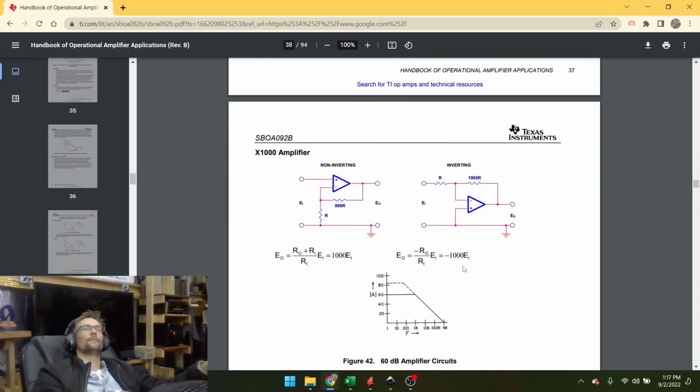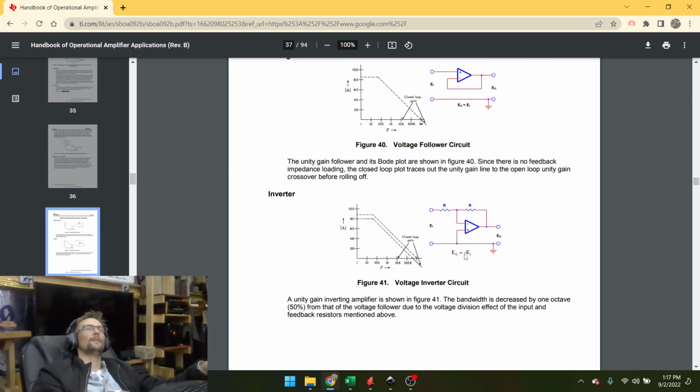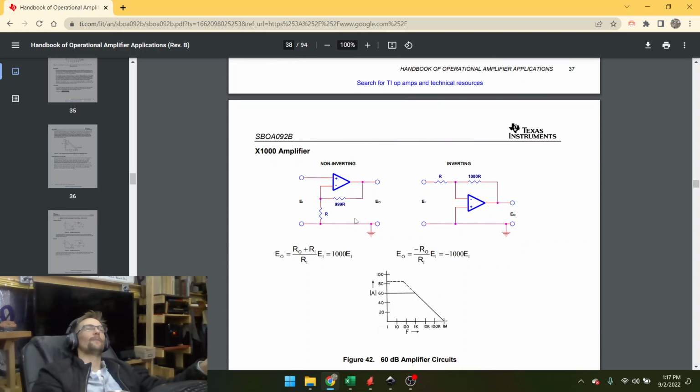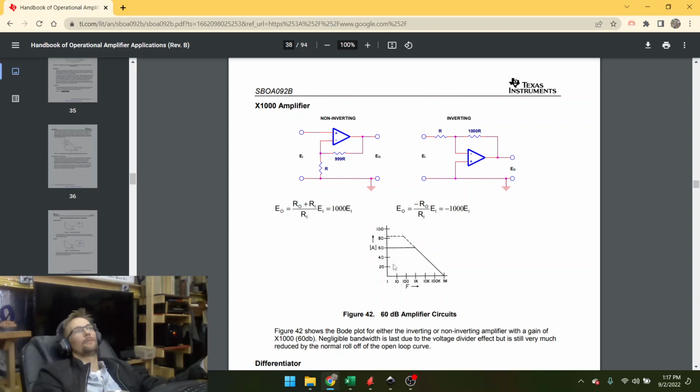So, yeah, that's just one of the things electrical engineers have been dealing with: the psychological negative sign in front of the inverting amplifier, and the fact that the inverting amplifier is better than the non-inverting in a decent number of real-world applications. It's because of the ground plane that you could just put on that pin.